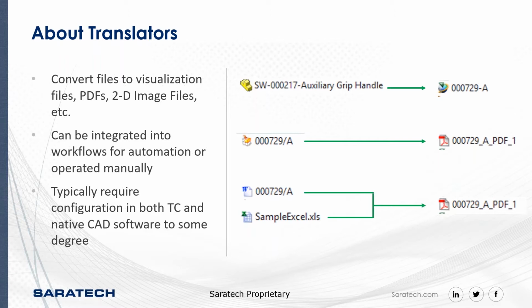Additionally, generally speaking, when we are working with any of our many CAD systems that integrate within Teamcenter, there is the need to configure the translator within the Teamcenter side as well as the CAD software side. So in some cases, your administration team may need access to not only your server machines to configure the translations, but also your client machines in order to carry out the necessary deployments. So just be aware of that when initiating these for your own groups and businesses.